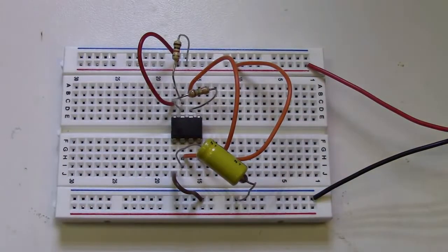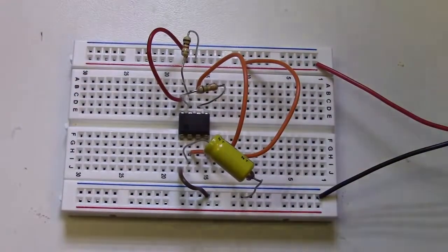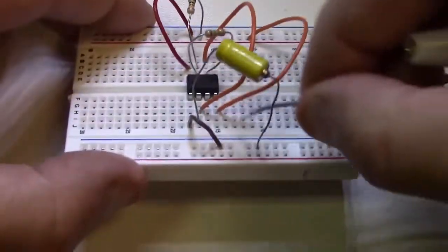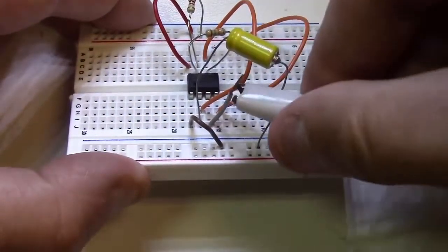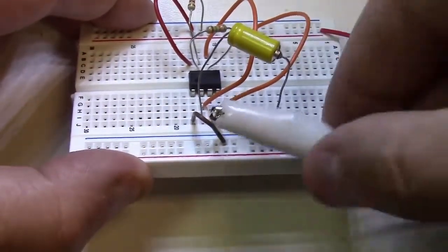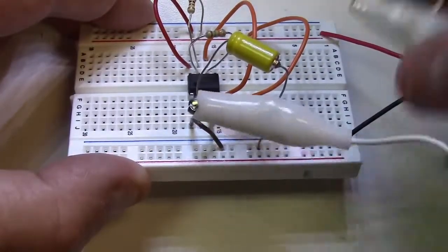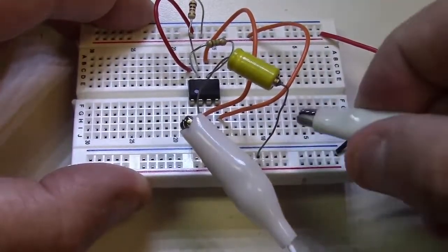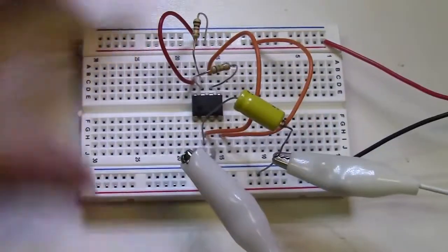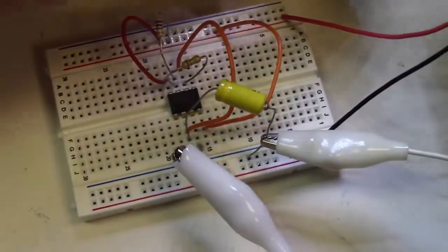The way I'm going to test it is using a speaker. This is going to be a fairly low frequency. Let's see what we got. So I'm going to put one more wire in here on pin 3, which is our output, and I'm going to hook into this, and that's going to be our output, and then we're going to hook this to ground. And since we already have this wire for the capacitor going to ground, I'm going to hook to that, and we're going to hook this to a 9-volt battery,